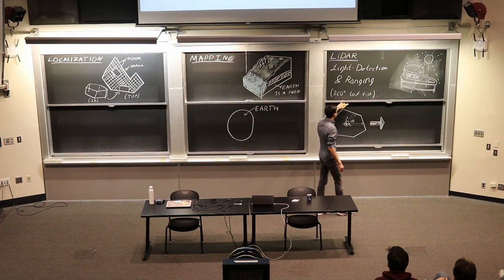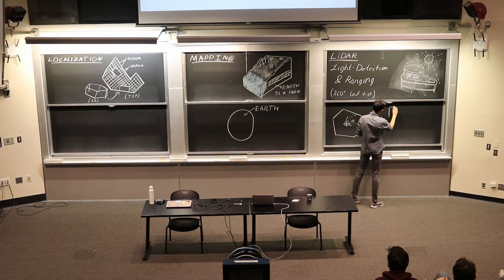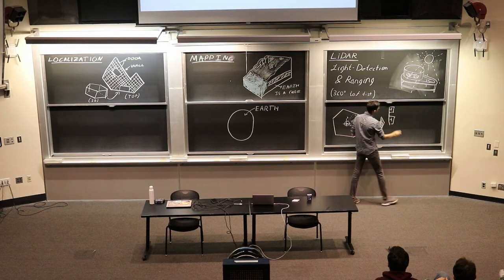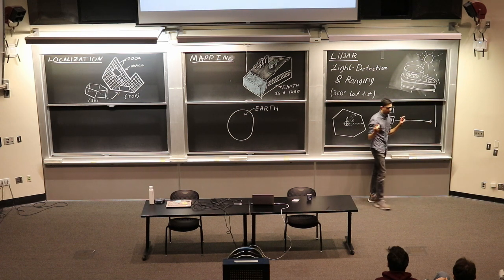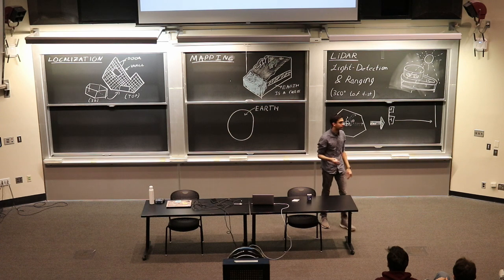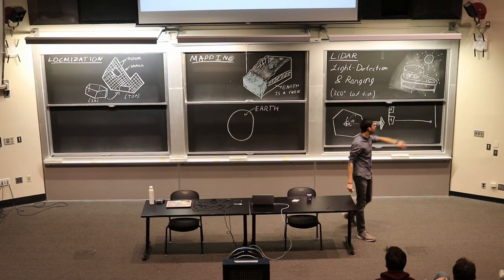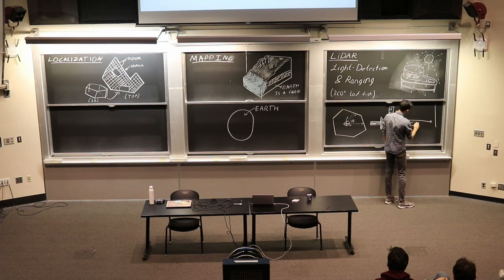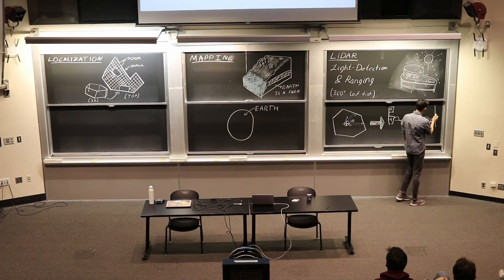sensor is. And a time of flight distance sensor, basically what one of these things does is, this is what a time of flight distance sensor looks like. There's a transmitter and a receiver, and here's a wall. The transmitter is going to send out some known wavelength of whatever, sound, light, whatever it happens to be. Ultrasound runs on sound. LiDAR runs on light. And it knows the speed of this wave. That's called C equals speed. And the transmitter is going to transmit a beam. It's going to hit the wall.